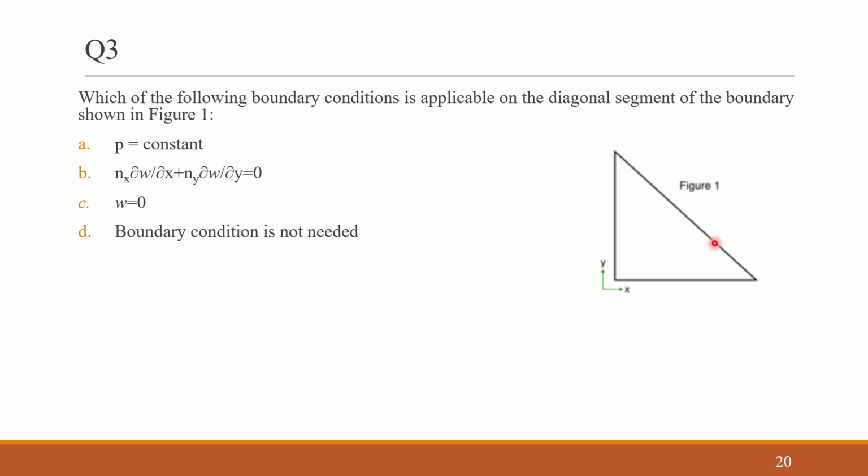In CFD, when we use the no slip boundary condition, we refine the mesh near the walls to a very fine mesh, so that we can appropriately get the true value near the boundaries.